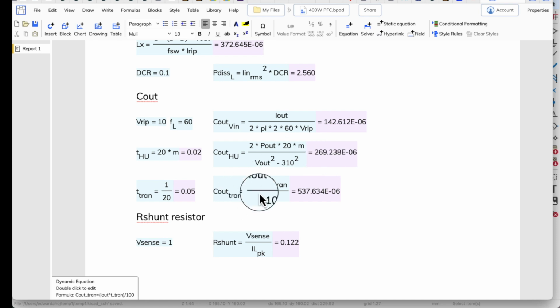This one down here at the bottom, I'm just saying I'm going to drop 100 volts, even a little bit more, because the next stage can regulate through that, so that's okay. And I'm going to go from 0 to max I out, which is about 1 amp. The transient is going to be 1 over 20 hertz, so maybe I have a 20 hertz note, right? And it's going to drop the power.